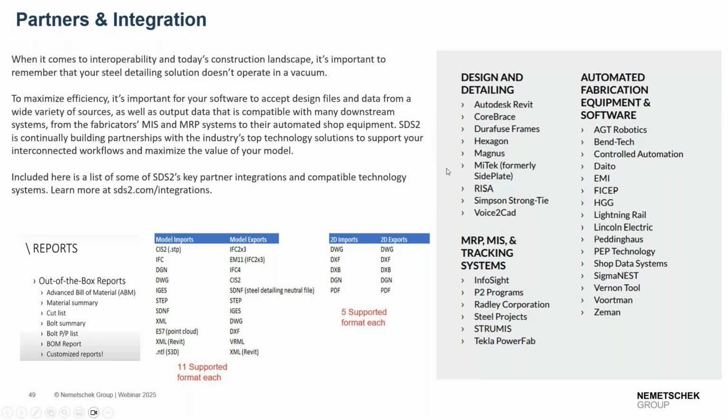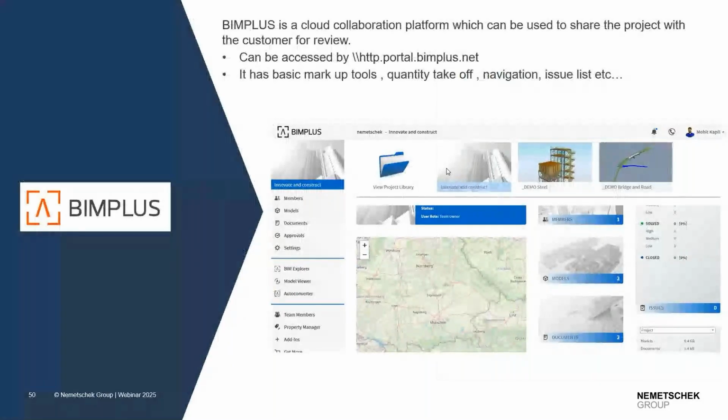Another feature SDS offers is BIM Plus. SDS has a cloud collaboration platform which you can directly access through portal.bimplus.net. You can upload your project here, and if you want to share it with your reviewer, you can share it. It has some basic markup tools. You can also include your drawings and connection calculations in this, and that model can be reviewed by your designer or structural engineer. He can mark his comments.